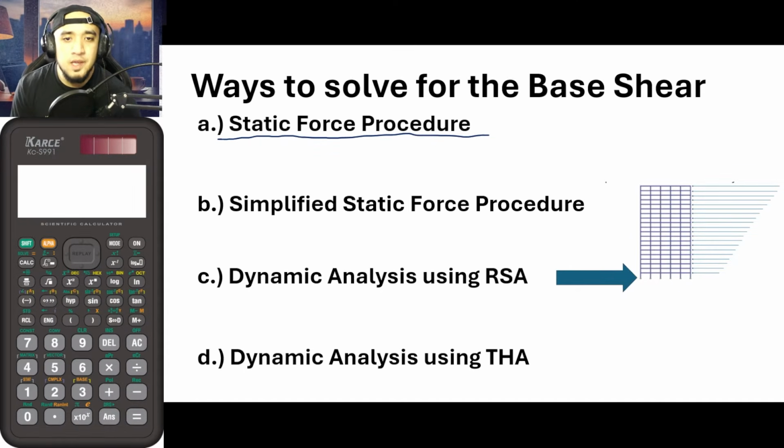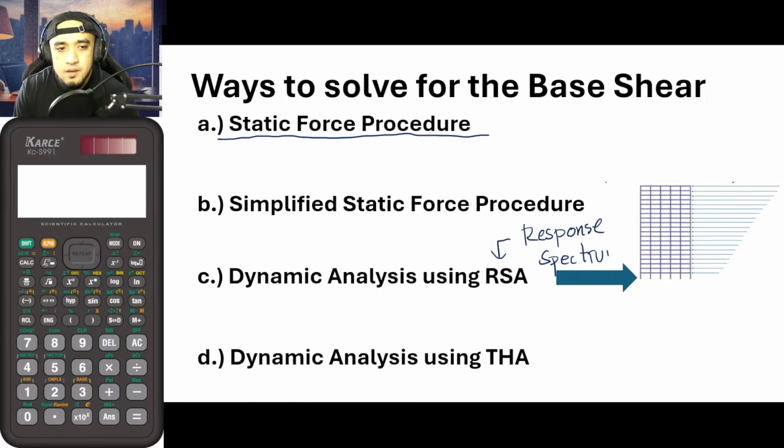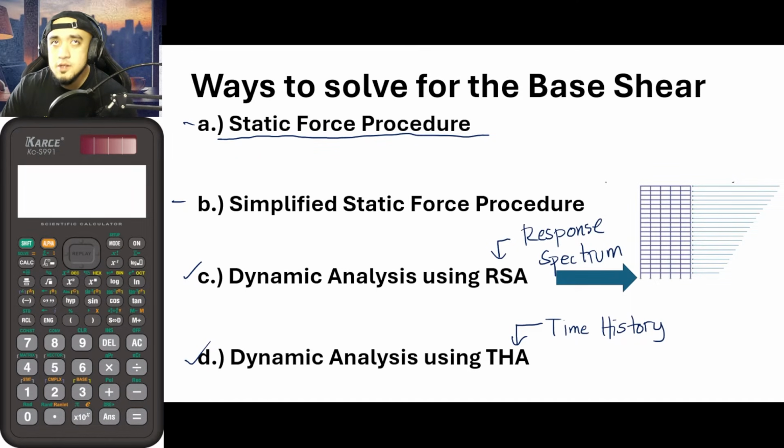depending upon their structure, of course. Okay, so the third one is what we call the dynamic analysis using RSA, or response spectrum analysis. And for the fourth one, this is now the dynamic analysis using time history analysis. So time history. Okay, so these two here are rather much more advanced than the first ones. However, guys, the dynamic analyses are the most accurate or the most precise analyses if you are solving for the base shear due to earthquake.